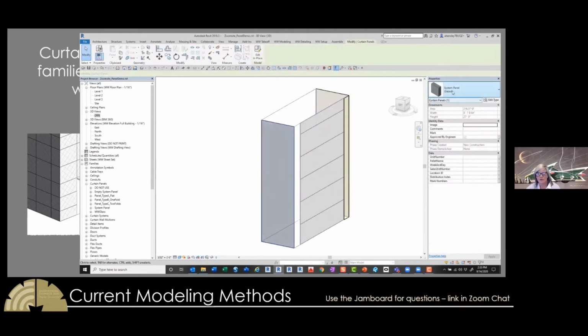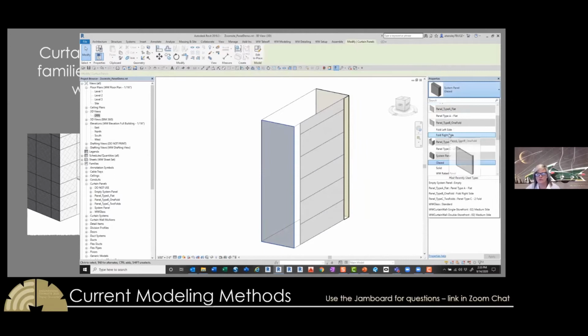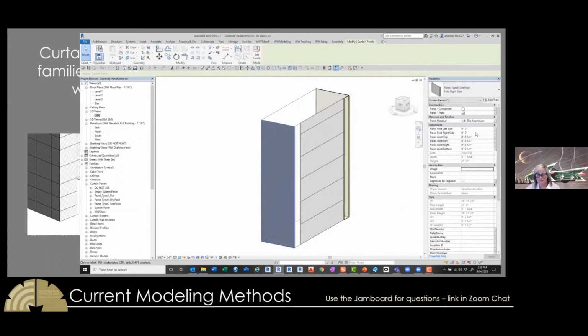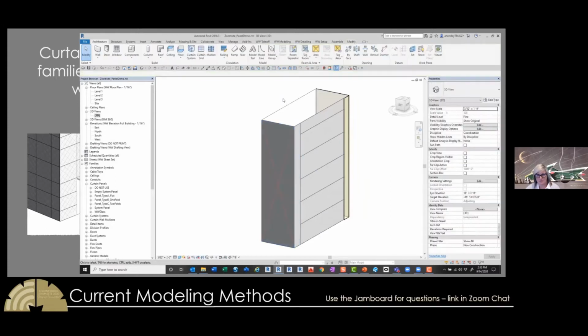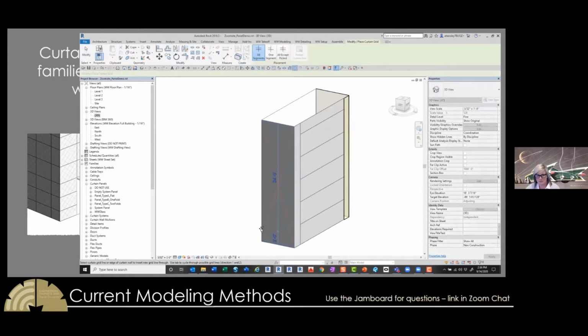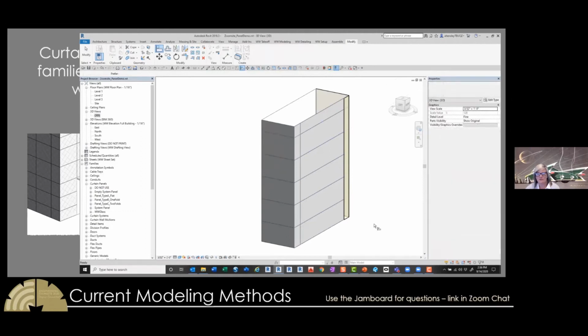And we're going to put a B-type panel where there's the fold on the right side in there. And then I'm just going to adjust that right side fold to be to the center of that joint, the 2'6". And now I'm just going to add the grids up the side to make those same joints. I'm not being super careful about it right now because I'm going to go back and use the align tool to get those panels around the corner to line up. Lots of different ways to go about it, different methods.